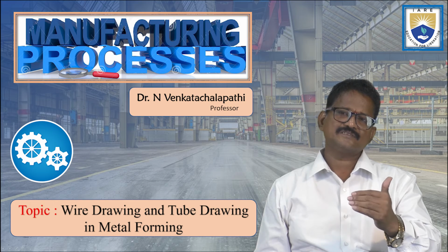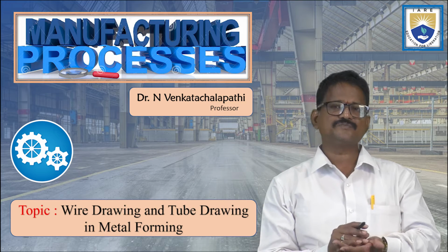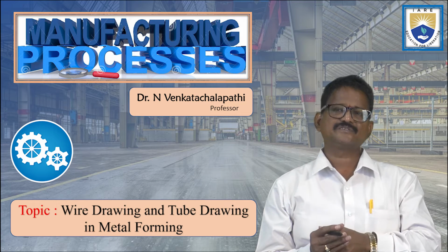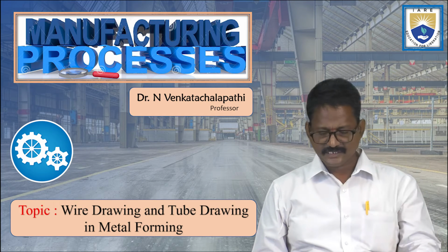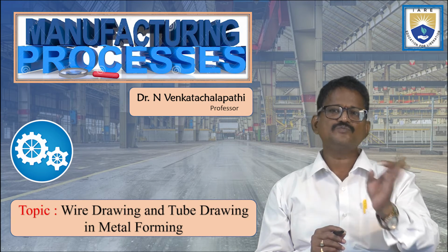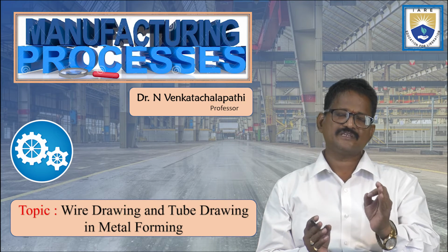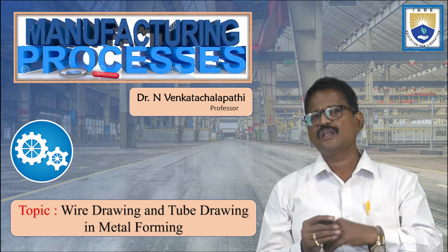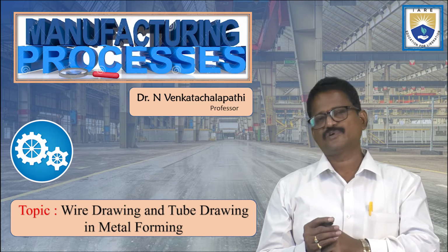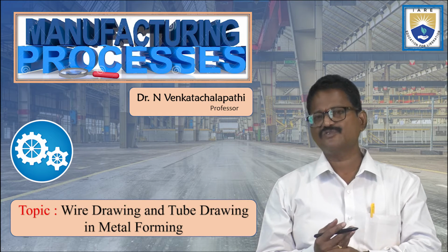Under the hot working process, the major applications are hot rolling, hot forging, hot tube drawing, or hot extrusion process. Similarly, when you are discussing the cold working process, the metals or materials are worked at room temperature. Because no heating is done, obviously you require a lot of pressure or high force to change even a simple shape. That is why wire drawing and tube drawing come under cold working processes.